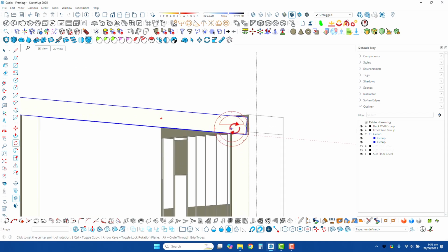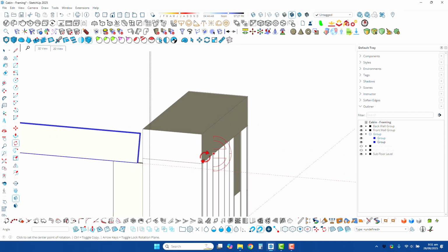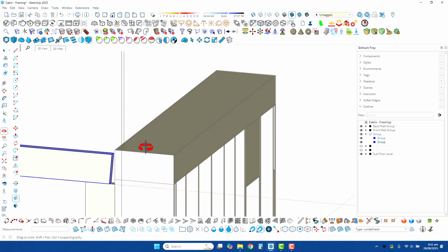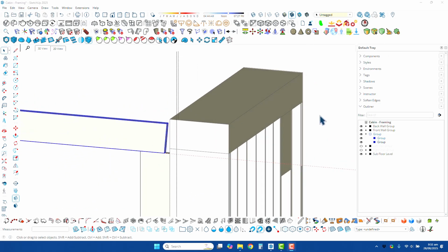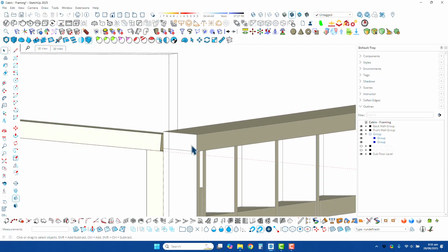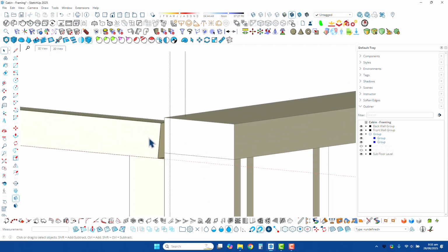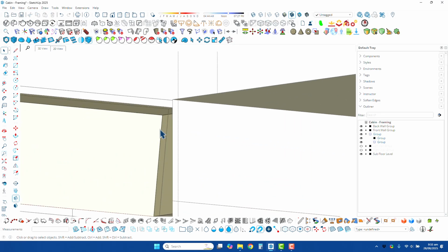But things aren't matching up quite nicely, so we'll look at how to use these tools to select lines and select corners and then close that gap up. Right, so to close the gap we need to zoom out so we can see what's going on. Select the member, or get into the group, double click, get into the group, then select our line.